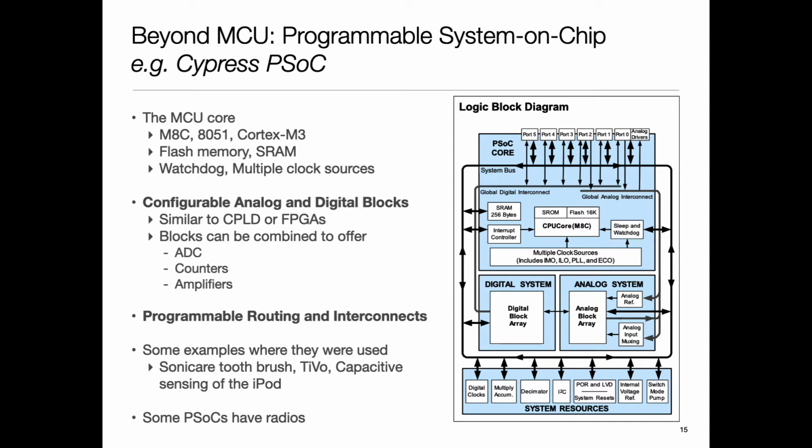So what has happened in recent years is this concept called chiplet. Actually, UCLA is pretty active in that. The idea is that you take little chips, pieces of silicon die for these different things. You get the best processor and the best radio and whatnot, and then you slap them on a bigger silicon substrate and wire them together. So it's almost like a hierarchical chip.